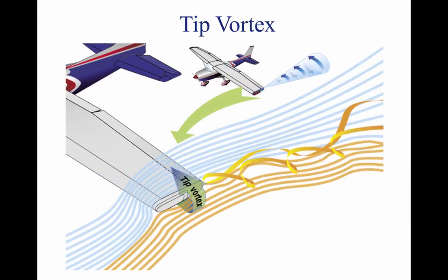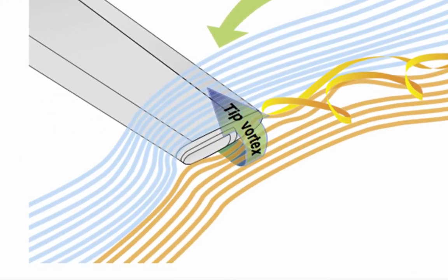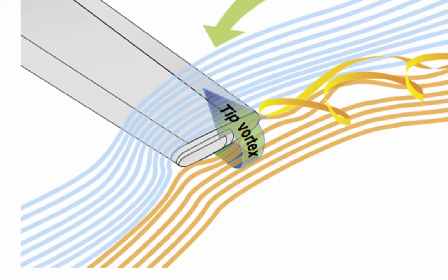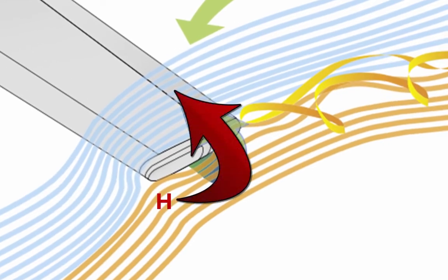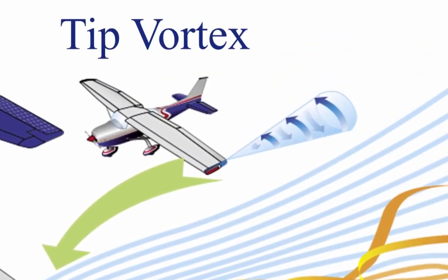When we talked about lift, we were talking about the lift caused by air flowing over the center part of the wing. If we look at the tip of the wing, there is a phenomenon that occurs known as tip vortices. When reaching the edge of the wing, there is still a low pressure zone above the surface of the wing and a high pressure below. These pressure zones naturally want to even out, so the high pressure air tends to flow towards the low pressure air. The high pressure area on the bottom of an airfoil pushes around the tip to the low pressure area on the top. This action creates a rotating flow called a tip vortex.